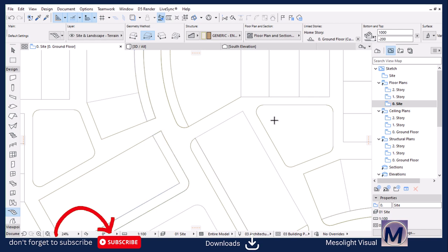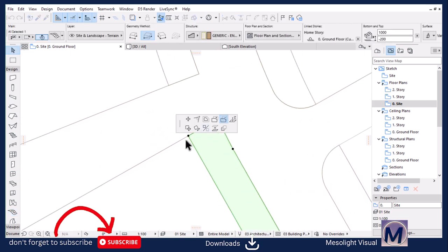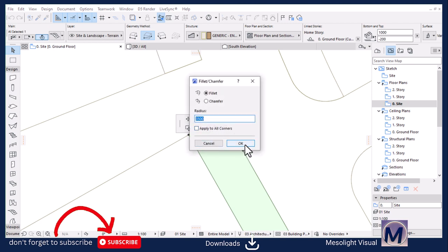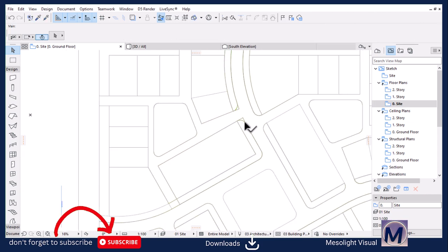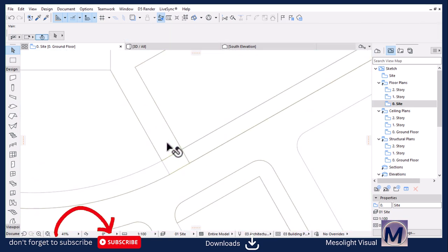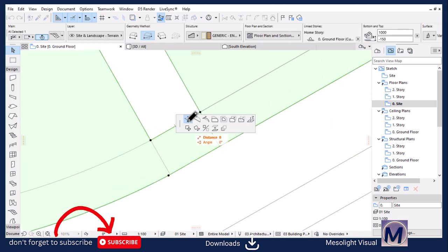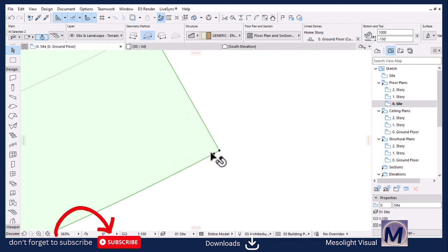Here we needed to round off this. I don't know why we forgot to do that, but we can still do it in our mesh. So select it and then pick the point. Let's use the round corners or fillet. Then you can still achieve the same results effortlessly. As you can see, what's remaining here is the 2D, but for now it's not that important. Let's see the situation here as well. This needs to be there. Select this point, fillet.